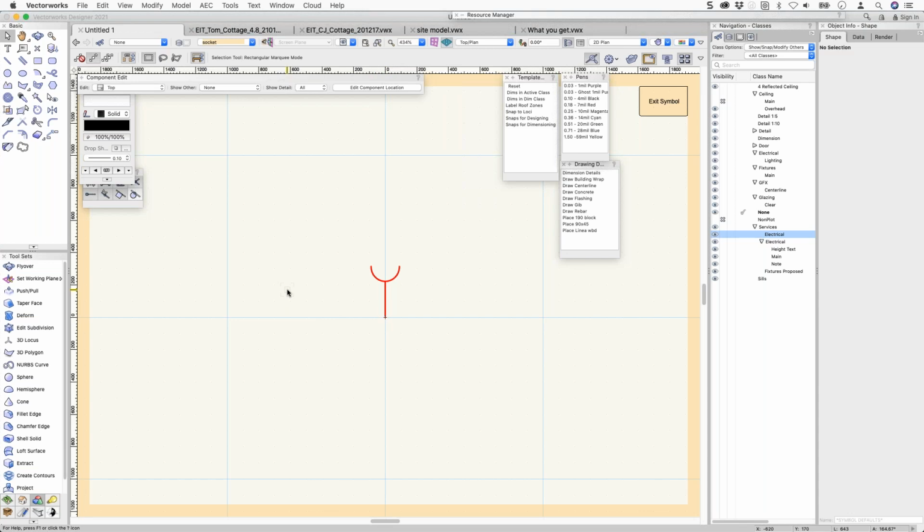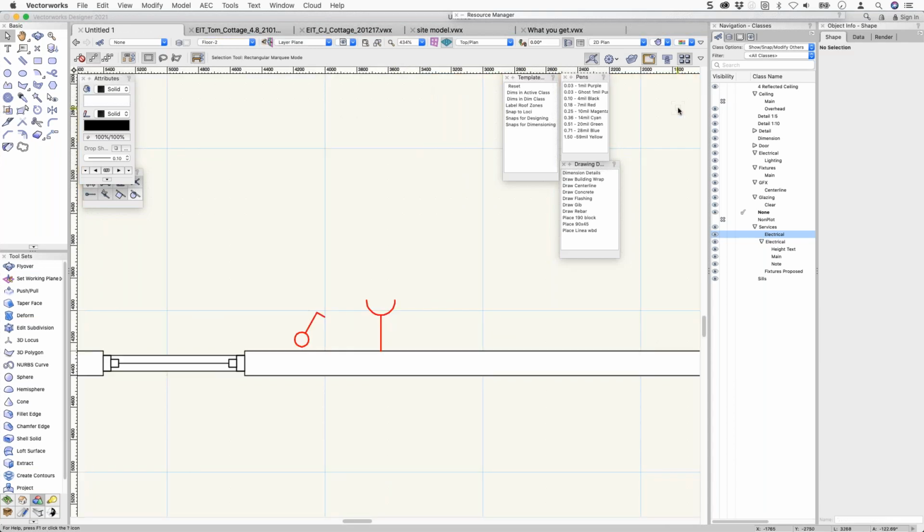You don't have to muck around with moving them. They stick on the wall. That part there's the bit that sticks to the face of the wall, and it just makes it really quick. You'll also notice that my line weight is red. It's red, but it's 0.18 line. So I'm consistent about the line weights. I'm consistent about the classes, and I build them into a library.